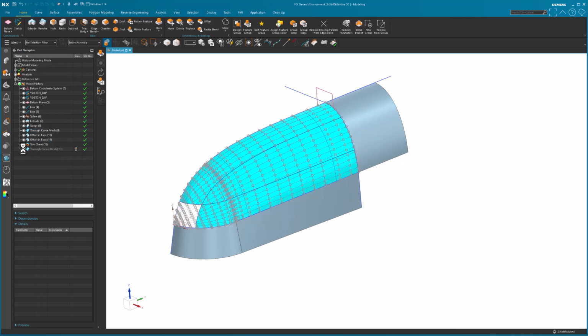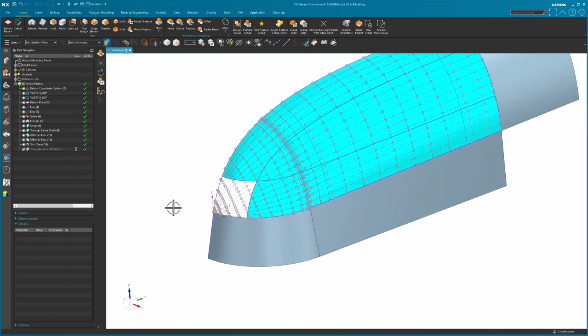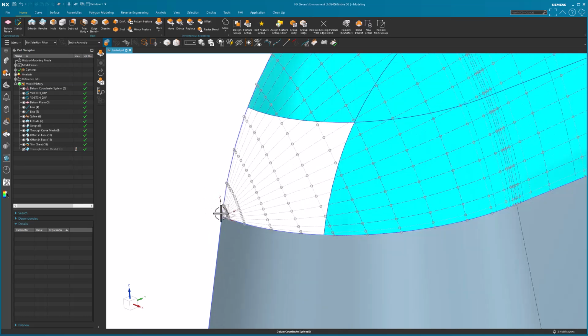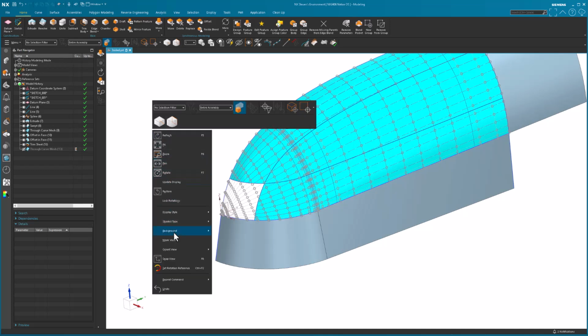And the initial surface is a three-sided surface. Let me hide this through curve mesh down here. That looks like that, right? And even though its input is a point, three sides, this edge or that end is infinitely short, right? Because all of the control points are now basically on top of one another right at that point. And so then he ended up trimming that corner out and then putting in a new surface, and complexity and so on and so forth.